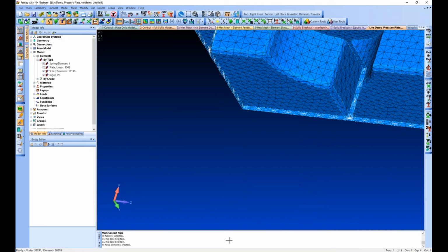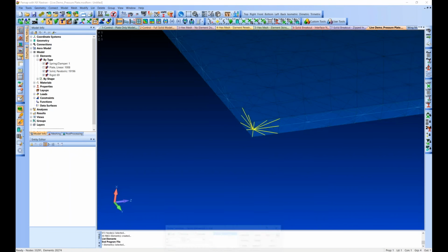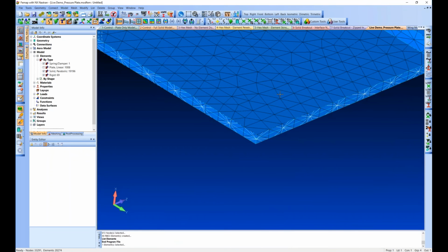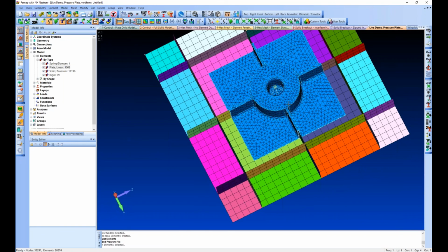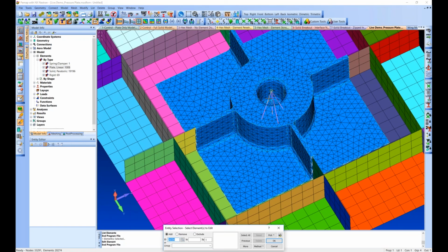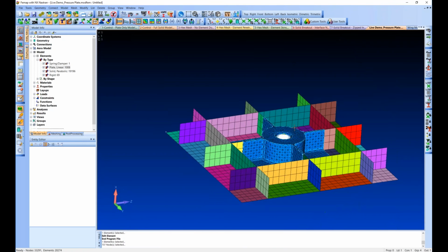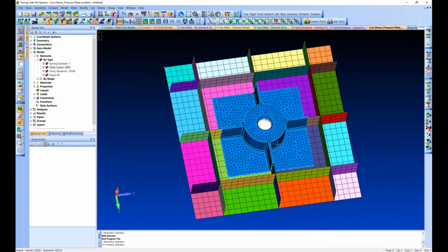So now you've got these. So you saw these in the previous example. These are RBE2s, but they're pretty good. They just reached out and they grabbed some of the nodes here, spidered them out. So a quick, easy way to do it. Now we're going to bring back our plates. We're going to just update this RBE that we have to manage our bolt there. We're just going to pick the surfaces on here too, just because it's easy. There we go, and there it is. So not too time consuming, right? Pretty simple to make, and it's accurate, right?